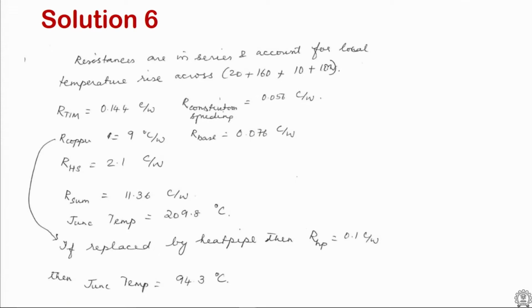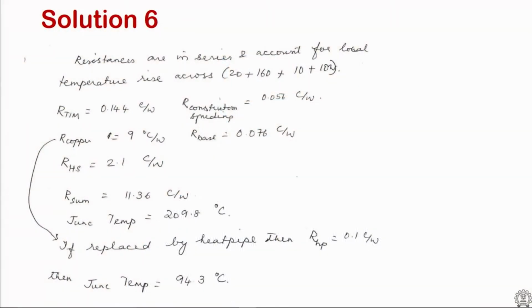And we will see that because this heat sink is mounted at the far end of the domain, the ambient air entering the heat sink will be much higher in temperature than the inlet to the system itself, because all the heat dissipated by the heat sources on the top will be dumped into the flowing medium.